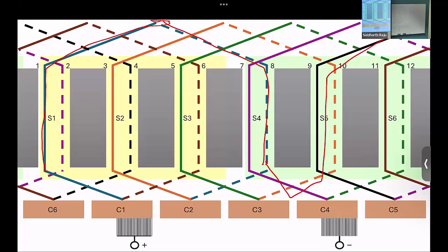You'll typically have a program. You'll tell the number of slots, number of windings, and then it'll wind it for you and show you how it is laid out. You'll tell what configuration you want. And irrespective of the number of poles you have, it will always be 2 parallel paths. All right. What will be the advantage of having more parallel paths? When will you use a motor with more parallel paths? When will you use the one with fewer parallel paths?